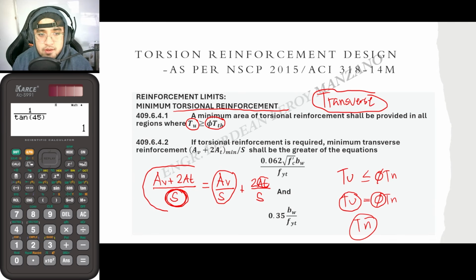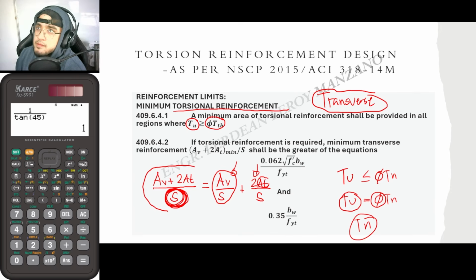Okay? So you already know this value, and you must be solving for this particular value for the effective. So with that, guys, again, you must solve for shear first, then torsion later, then combine their spacings in order for you to get the required spacing. So in the next video, we would now be solving for a sample problem.